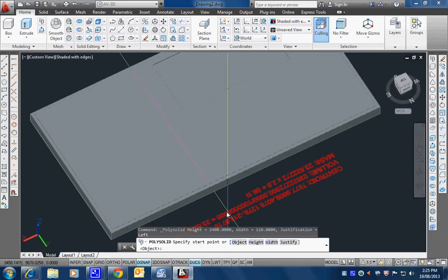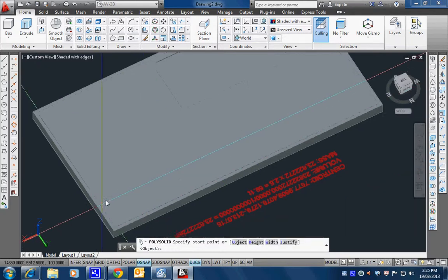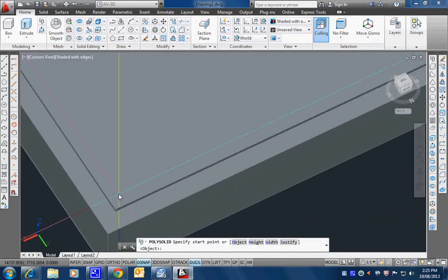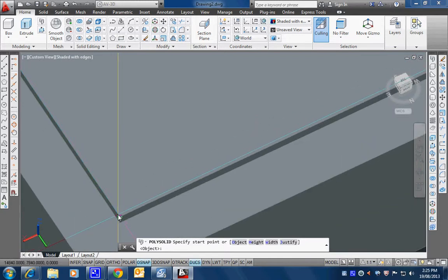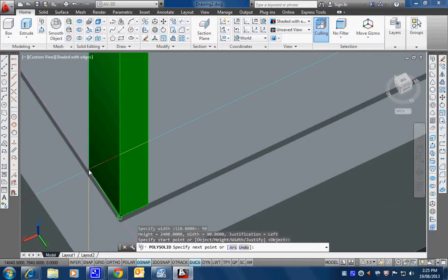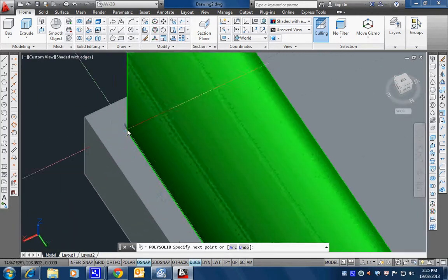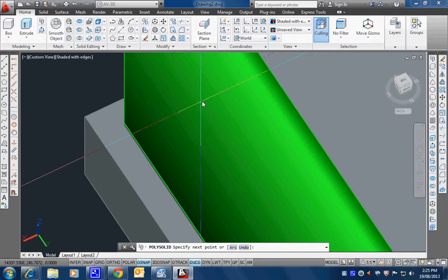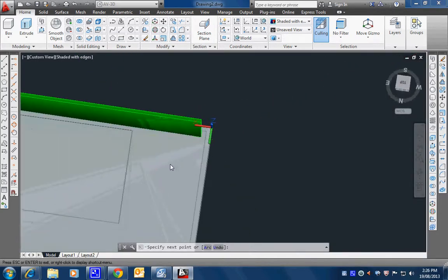Now everything is sort of set up except for the width is not quite right. That should be 90 now. Enter that. The 50 millimeter gap is automatically sorted out for us by this rebate. So if you start from there, it will automatically allow 50 millimeters for us. Okay, so let's go with another endpoint here, and over here we'll just swing around a little bit.